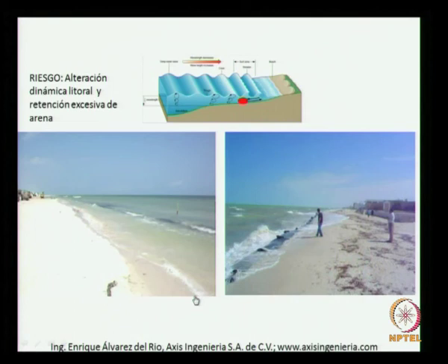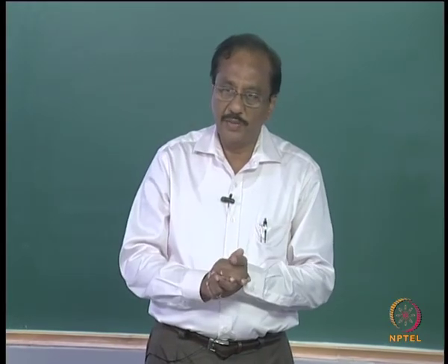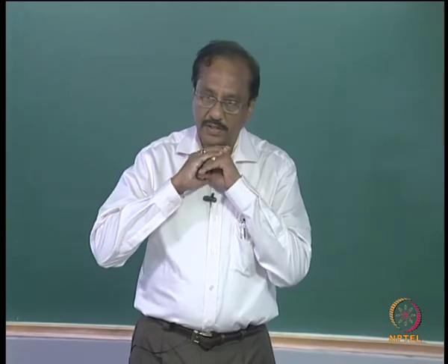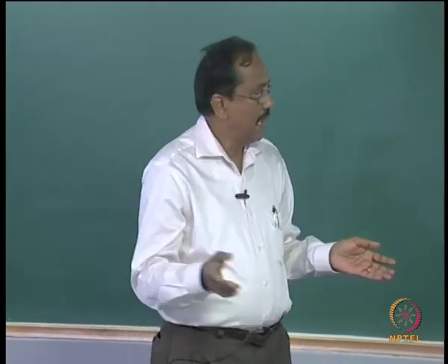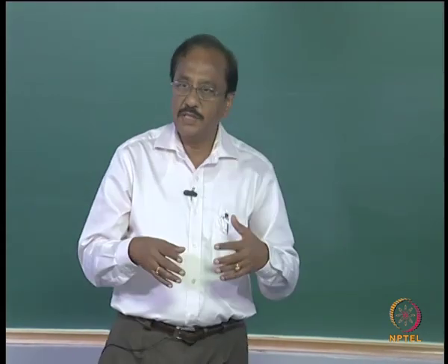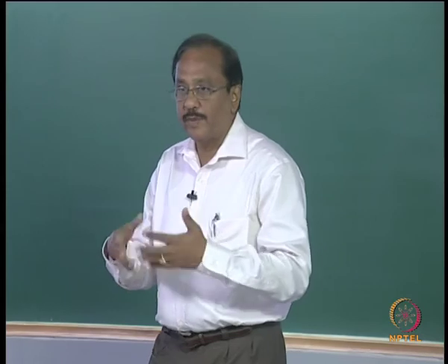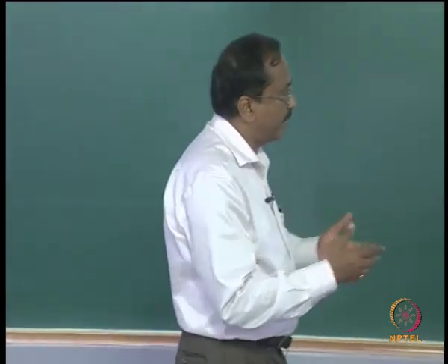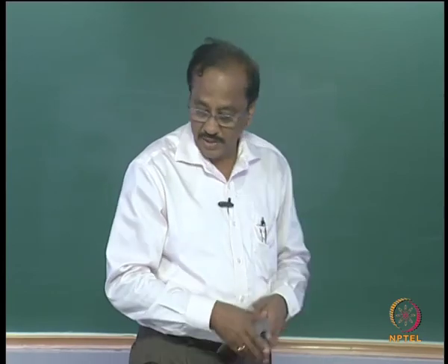I should place on record my sincere thanks to Access Engineering, who are the main consultants for these two projects. So this will give us a clear indication, as here they have adopted a submerged geotube. The idea is that a submerged geotube will allow premature breaking and dissipation of wave energy, and because of the dissipation of energy you can have an enhancement of beach formation. So not just protecting the coast, it will also enhance the beach formation.